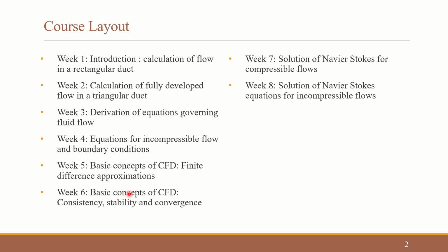In the continuity equation for compressible flows, density will be present. Also, it will be present in the momentum conservation equations. Whereas in the system for incompressible flows, it will be absent in the continuity equation but present in the momentum conservation equation. So it becomes an issue.